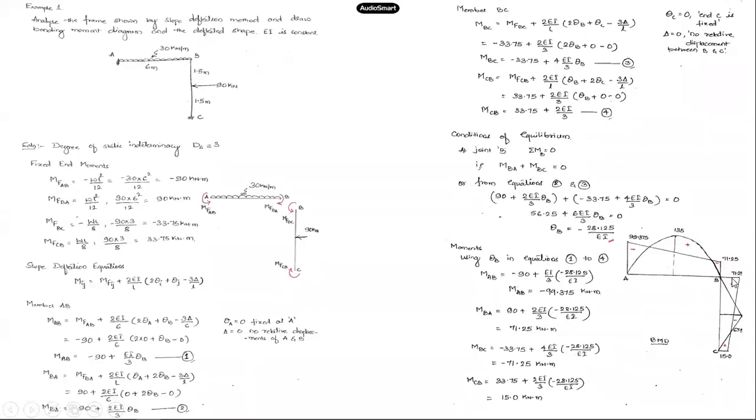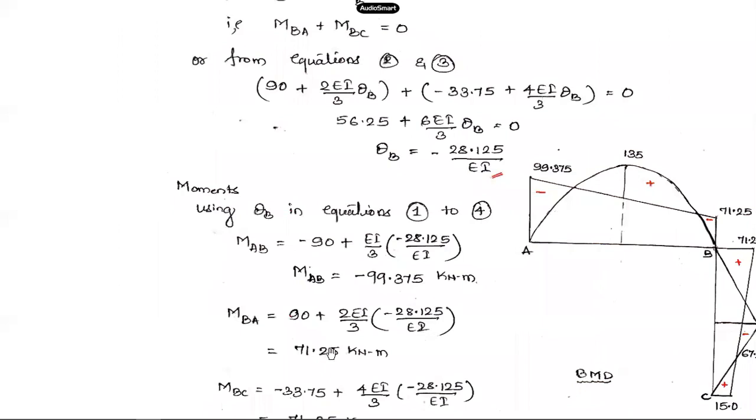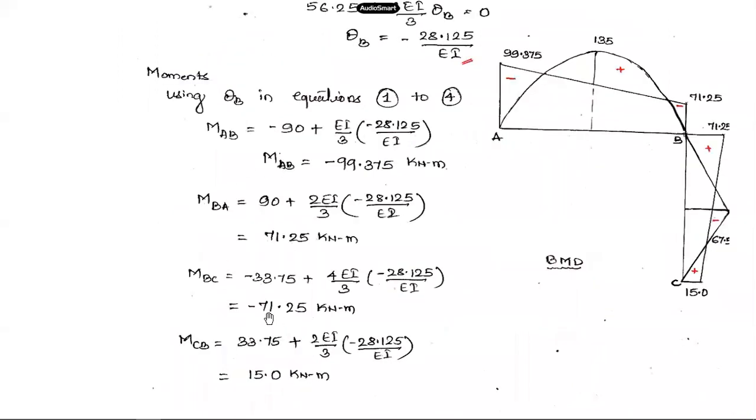But what is important is, how do you take the ordinate for these vertical members? Take the direction of the moment, apply it over here, and see how that member is bent about this joint. Here at B in member BC, the moment at joint B was anti-clockwise. So when I apply an anti-clockwise moment over here, it will be bending towards right. So this is taken towards right.